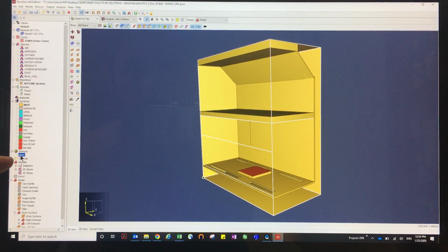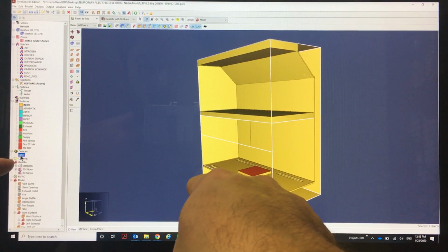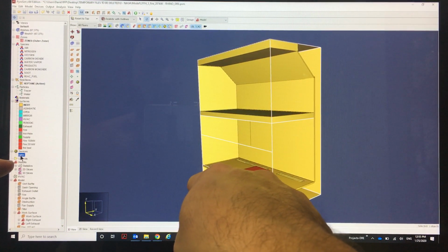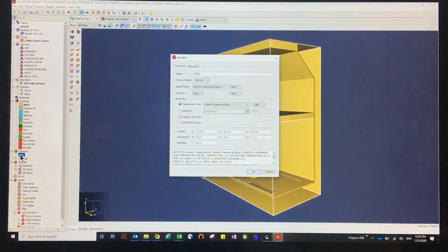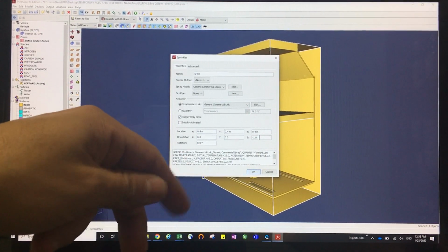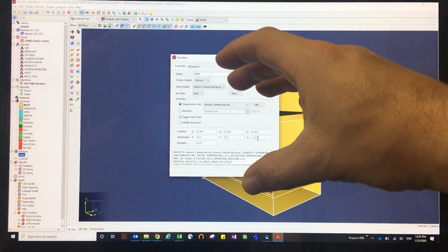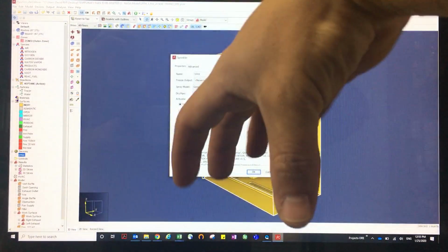Now, why don't I see anything here? Because I actually set it to the 0, 0, 0 coordinate. If I want to change that, I double click on it here, location, and here you figure out where you want it to go. I'll do it real quick just to show you. As the location, and then if you want it to be upright versus pendant, you mess with the Z. Z is -1, which is pointing down.